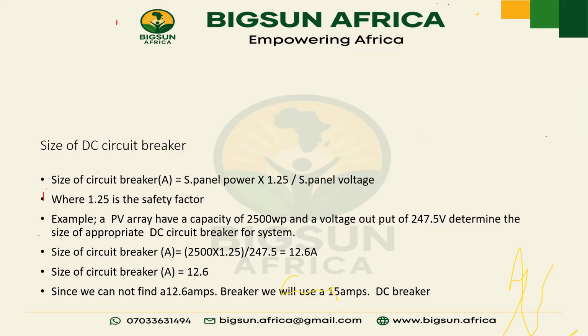Sir, the solar panel voltage, is it the system voltage? Yes, your connection voltage. Not the VOC, sir? No, not the VOC. Okay, sir, I understand now.